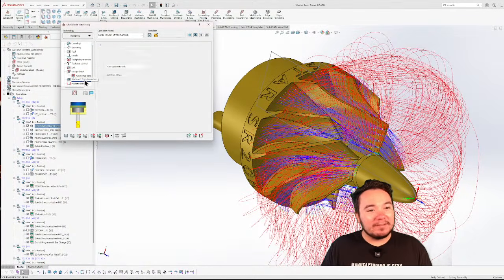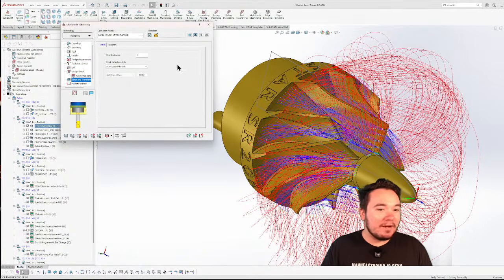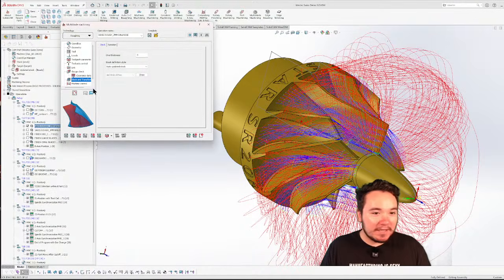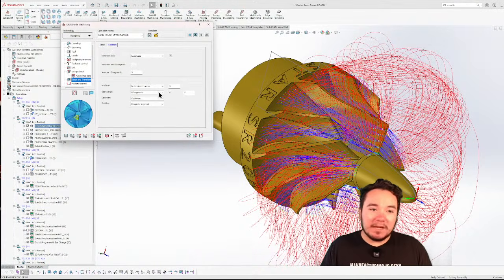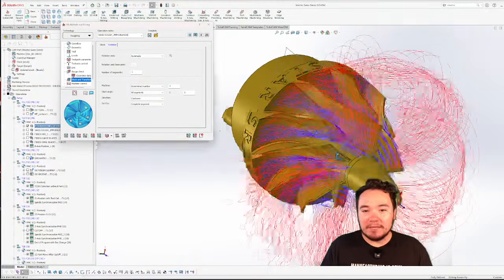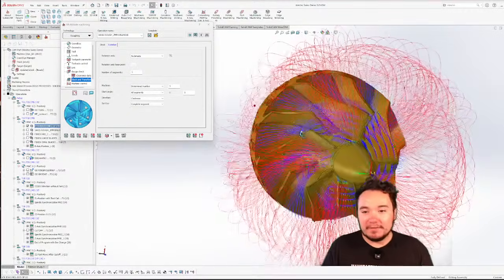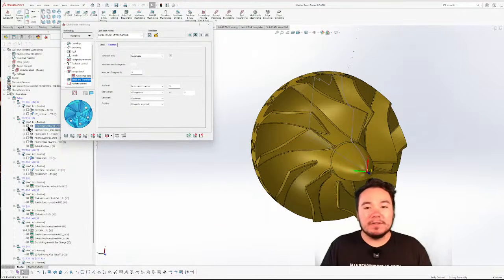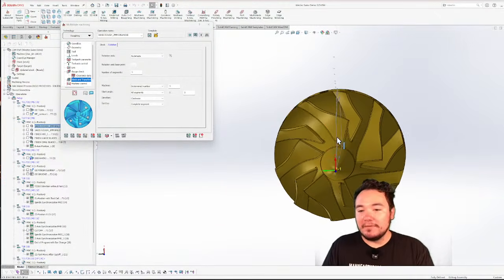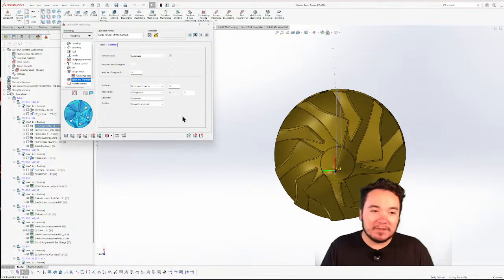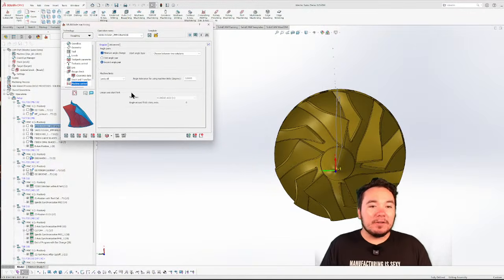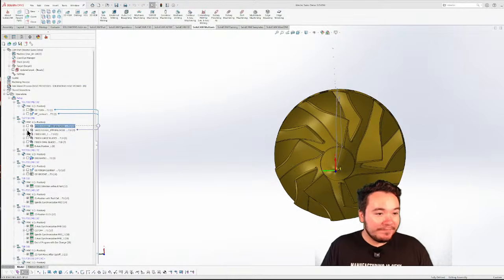All right, so where did I leave off? Stock definition, I let it do updated stock. So as updated stock calculates up here, that's what the program or the operation is looking at. And we did have to add a rotation. That's pretty much a translate if you'd use it for other operations. And so just translating it 5 times, looking over here, how many different sections are there. And it was pretty much good to go. And that's it for that toolpath.